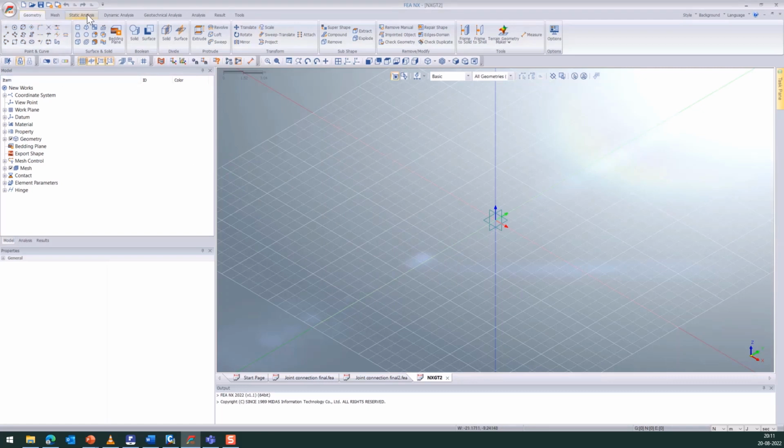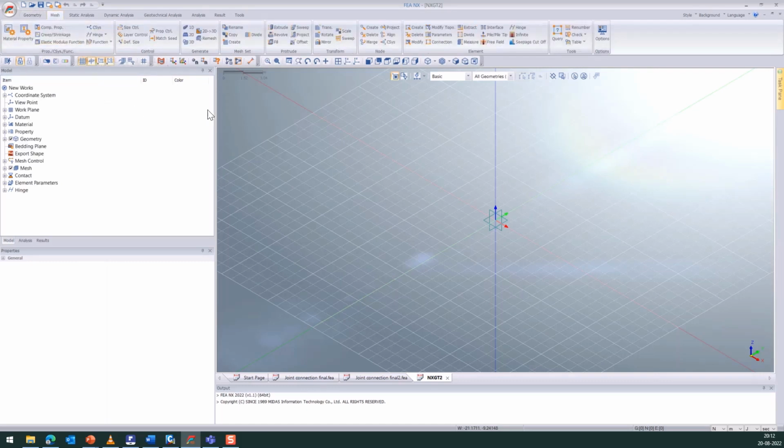This is the main menu, which is created intuitively for the engineers to be used in the order of progression of the model. So since it's a object oriented model on the software, first we define the geometry, which may be point, curve, maybe surface, maybe solid. Then we mesh the geometry to create nodes and elements.